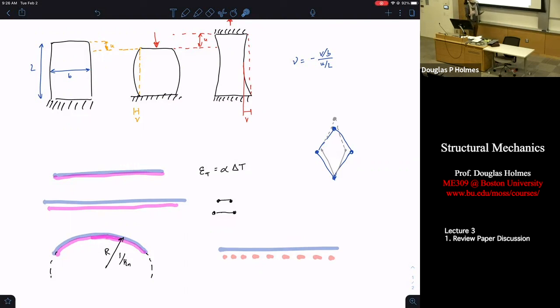So going back to the wafers problem, what's happening is that you have this material, probably it's not being heated uniformly. Most likely you put it on a metal rack in your oven. That metal rack in the oven is a little bit hotter than the air, so the bottom of the rack is hotter than the top. And so this whole thing is trying to warp. And the whole thing is trying to adopt a natural curvature that's exactly based on this bimetallic strip idea. And so it's trying to warp into a sphere.